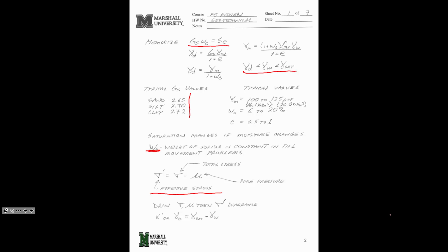We can calculate or measure pore water pressure. Take the difference, and that gets our effective stress for us. Effective stress controls everything in the geotechnical world. So that's why that equation is so important to us.